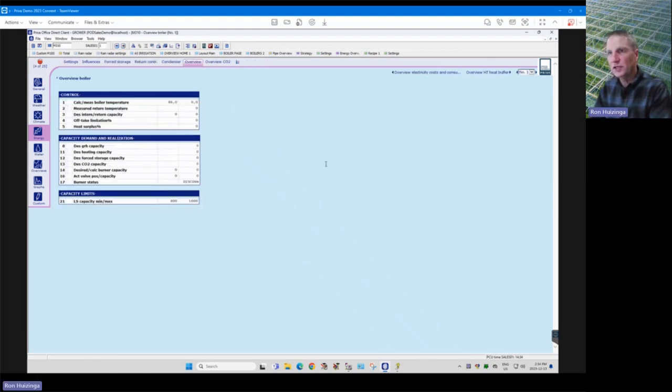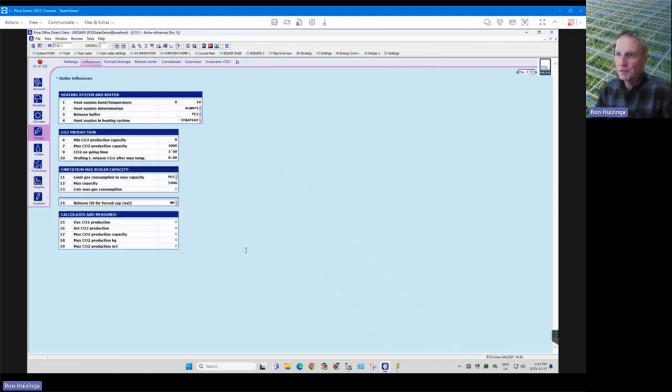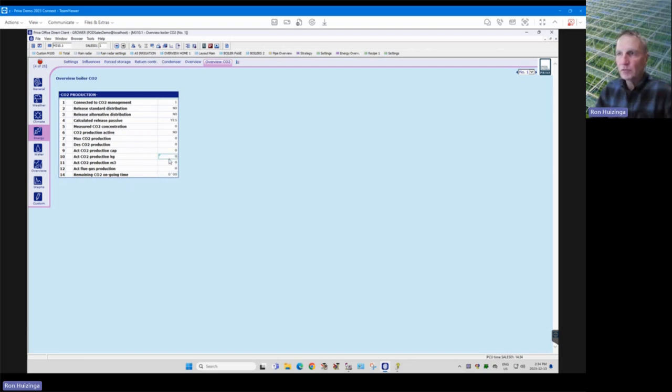One thing you can usually see here when it's running, it'll actually be a setting. It'll show kilograms of CO2 when it's running, so you can see it at that point. If your boiler is running at so many kilowatts, it'll convert it to kilograms of CO2 right here. Typically it's a straight calculation of 1.8 kilograms per cubic meter of gas. I don't think anybody's changing those numbers, so there should be a straight conversion from there to here.